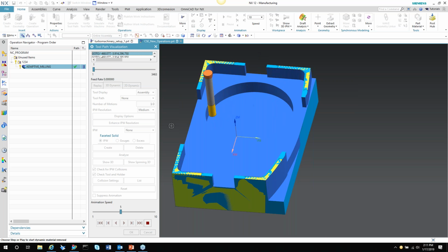It easily and quickly removes material. And I've cut material with the correct style of end mills up to 70 Rockwell with this cut pattern. The cut load is so accurate and so stable that it can easily cut. With the correct tooling, it can cut 70 Rockwell.